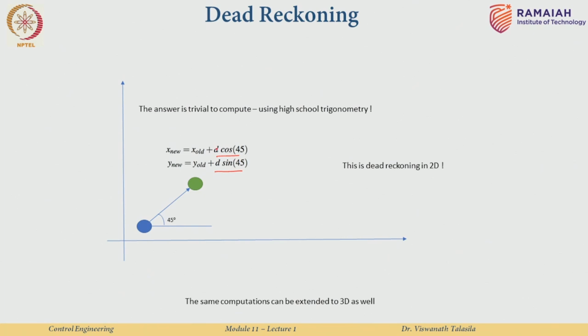Okay. So, this is basically dead reckoning in 2D. Note that we are not talking about accelerations, velocities and other kind of things measured by sensors. We actually know at what speed we are travelling, like how the ancients would do, have an estimate of the velocity you are travelling at, and based on that you actually calculate your current position.